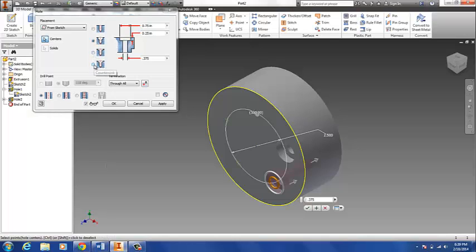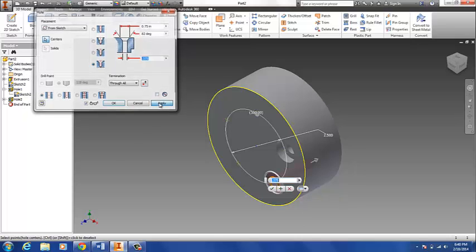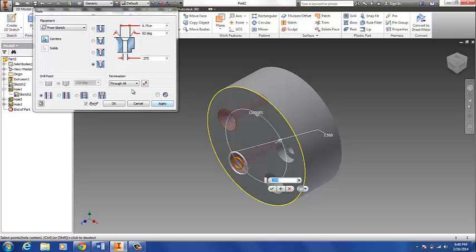Okay, so countersink is the 4th option. And actually the default options here are the correct ones. So we have 0.375 for the main part, the countersink a diameter of 0.75, and that's angled at 82 degrees. So we'll apply that. All right, moving on to the next one, we will unselect the 5th hole,